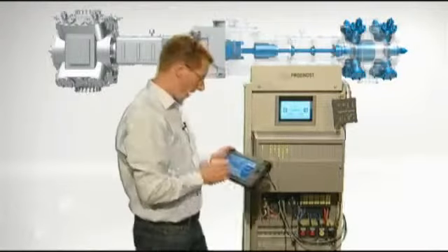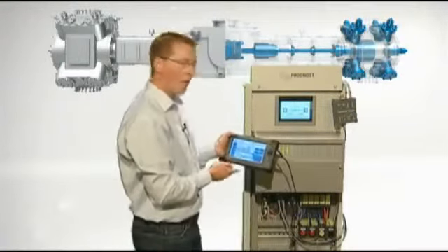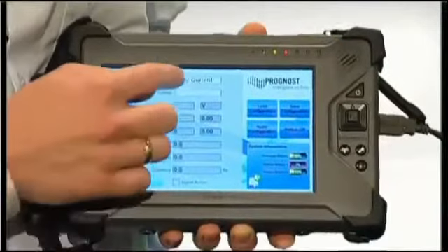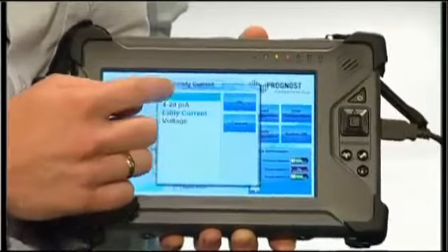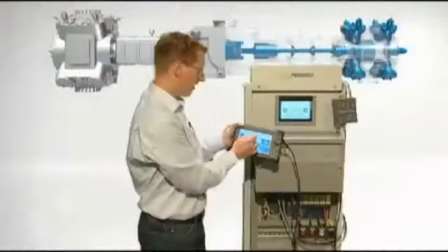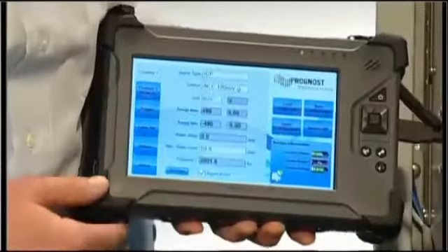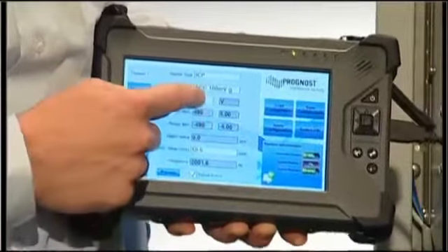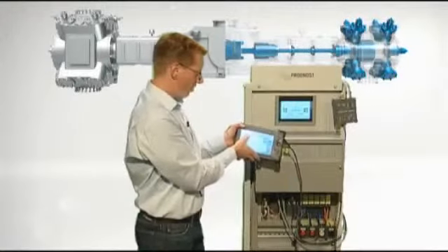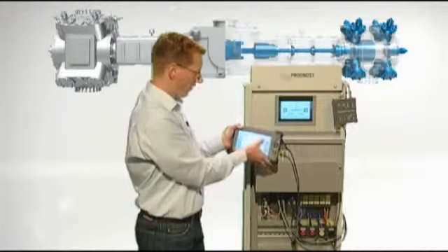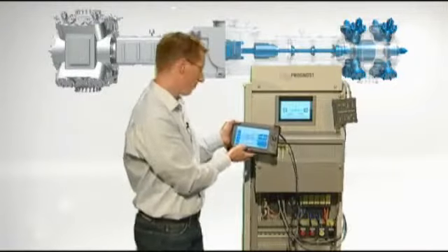So in the first step, I would like to change the configuration of channel number 1, which is now set to the signal type ICP, an acceleration sensor of 100 millivolt per G. It could also be different other styles. Unit is meter per square second. That could be German, UK, US. Let's stick with SI units in this case.